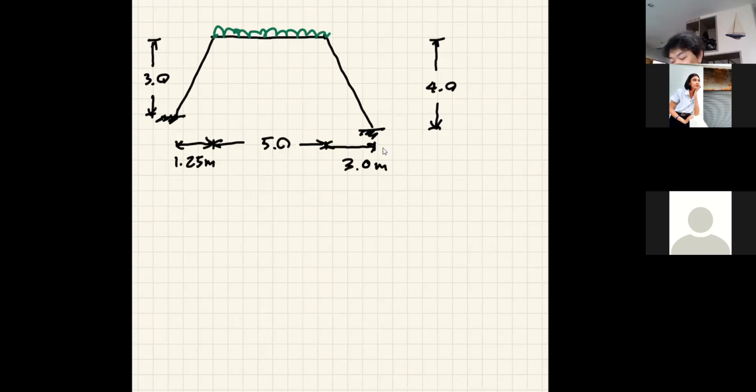So what do you think? Would this frame sway? What do I expect, right? Total quietness. So it will sway because it's unsymmetric. Regardless of whatever you have, we have the unsymmetric structure, so definitely it would sway. Now, you need to understand that we always need to identify the unknowns correctly first.